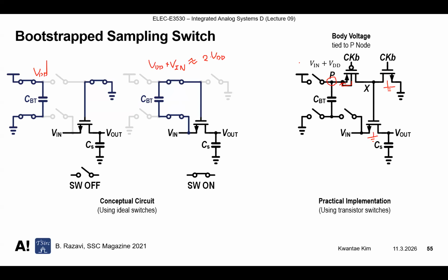So this can be very stressful for the transistors. In our process technology, we use a 1 volt supply voltage. That means that is the maximum voltage this transistor can tolerate. Of course, there can be some margin. For example, the fabrication and device engineers make sure this transistor can endure as high as 10% higher voltage, for example up to 1.1 volt, 10% margin there.